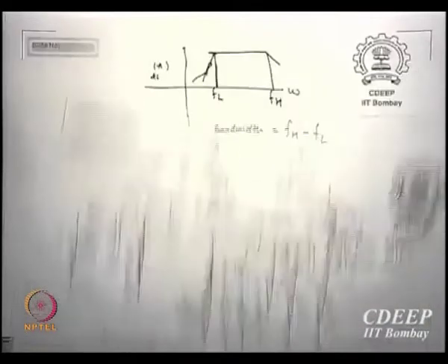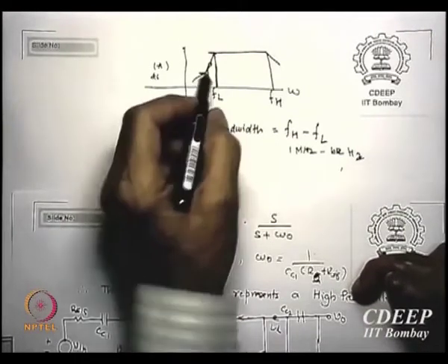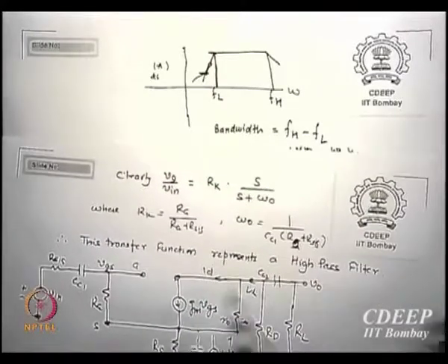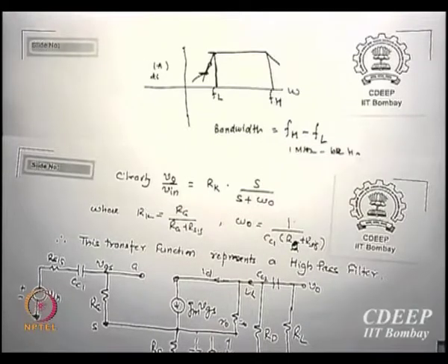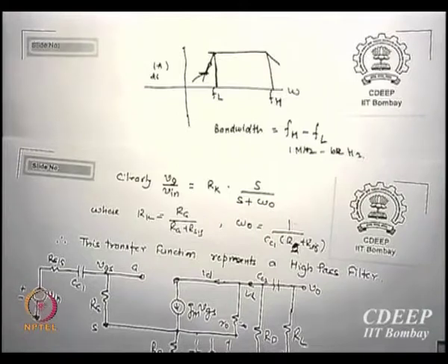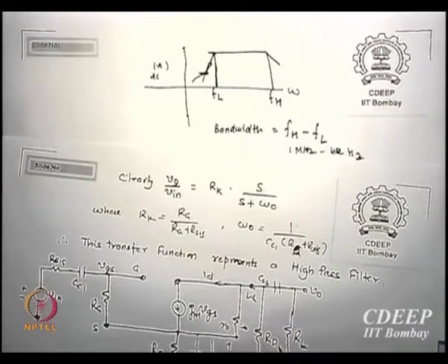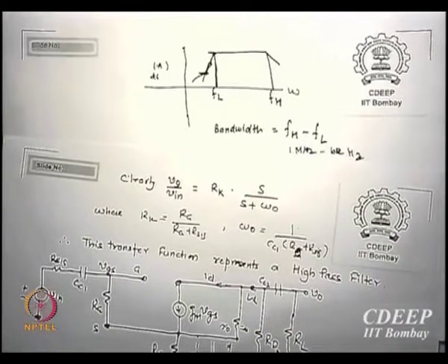For example, this figure, this is the value which we are talking about. S is the numerator. Essentially it says that there is a 0 at 0 itself. That means beyond that the gain is rising anyway. When S is 0, meaning omega equal to 0, the 0 occurs, which tells that the 20 dB rise should start right from the beginning. But this other value, the lower one, is a pole, which also is now increasing because of the S upon term.